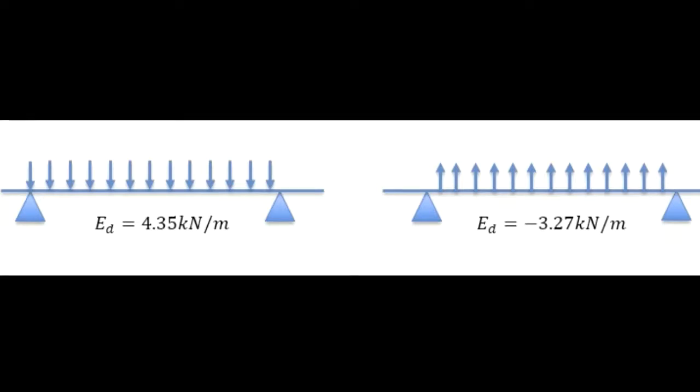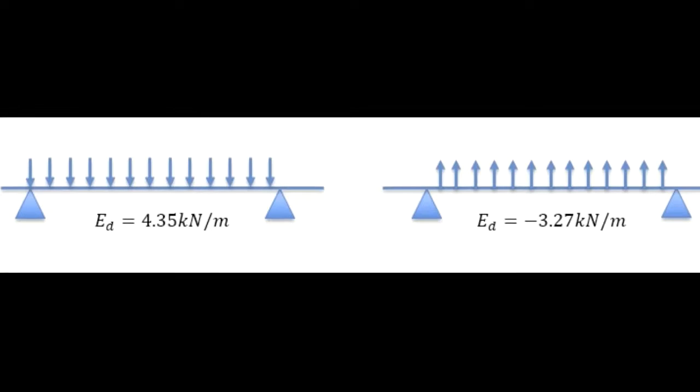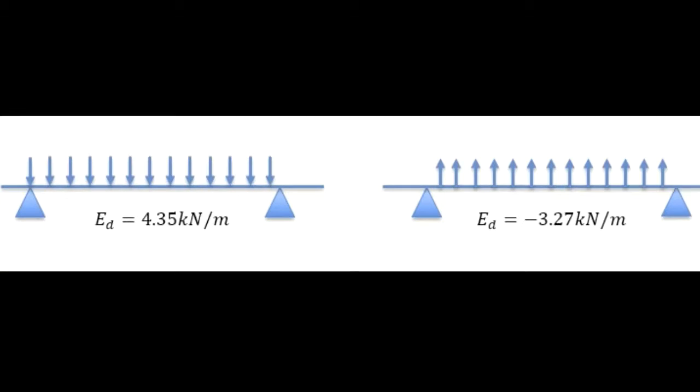Bridging. One row of bridging is needed. The test girt has an inward capacity of 5.24 kilonewton meters and an outward capacity of 5.24 kilonewton meters, which are both greater than the required values. Therefore, C250-24 is inadequate for the ultimate limit state.